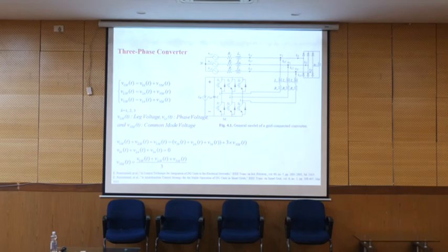It follows the voltage and frequency of the system, and it can support the stability of the grid. If something happens in the voltage or the frequency, we can adjust the active and reactive power injected and keep the stability of the system.